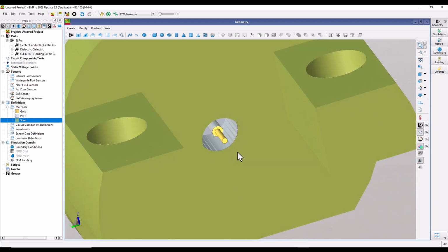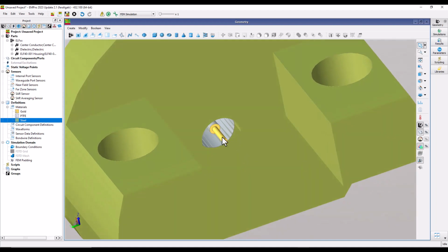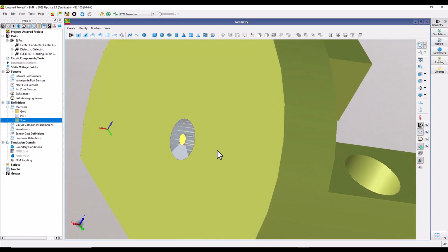The most important thing here is actually the center pin, which is going to land on your board, because that is where you may have the impedance transformation or impedance mismatch when you are launching the energy from the coax to your board design. Because remember, on this side you have a nice coax, which has full, proper propagation.